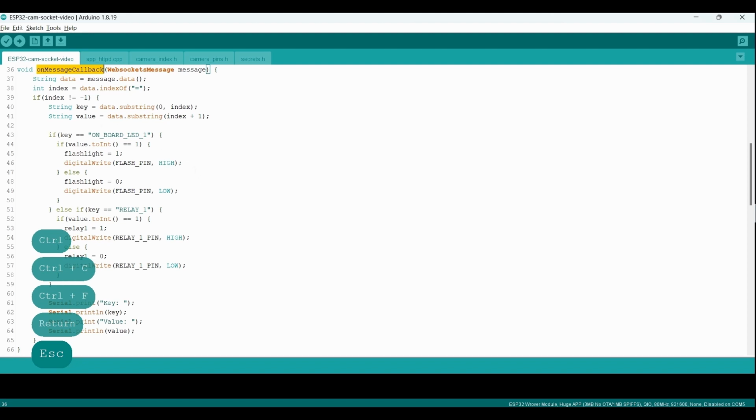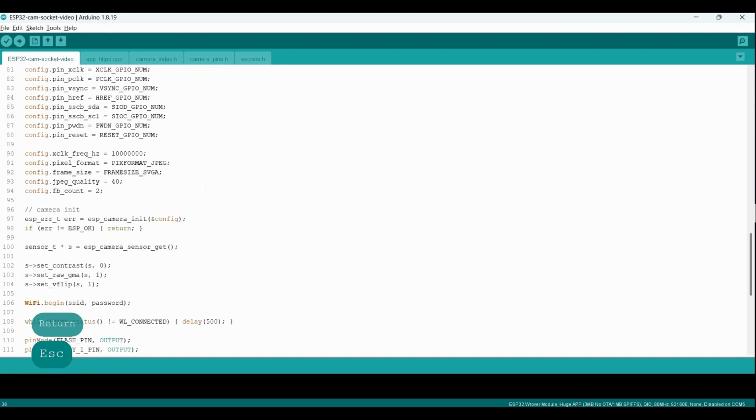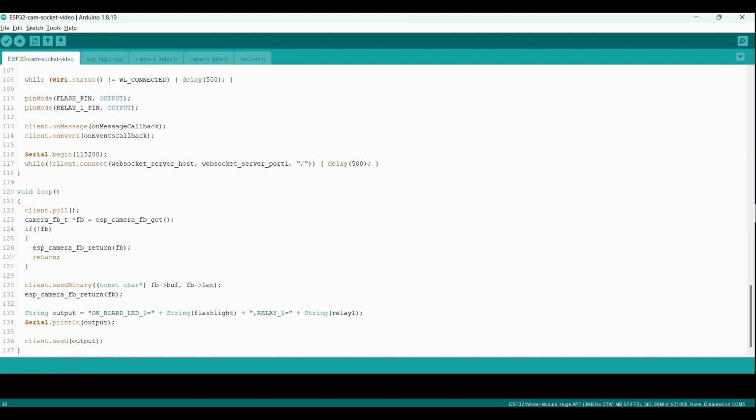The relay receives a high signal to turn on the connected peripheral. The variable holding the state gets a 1 instead of 0. The new state is sent back to the server, causing the icon on the dashboard to turn yellow. This allows the client to send the next command of 0, which turns off the relay. And that concludes this tutorial.